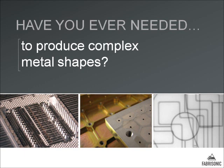The example on the left is a satellite component that has very deep and sharp channels built into it. Because we build this one layer at a time, we can come in with a very small end mill and make a very sharp edge in a three-dimensional buildup to make very fine features that are very tall and cylindrical and high. In the center is more of an aerospace product where we've built up material just where we need it.